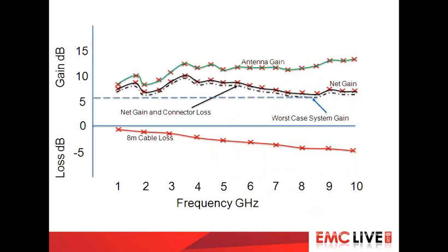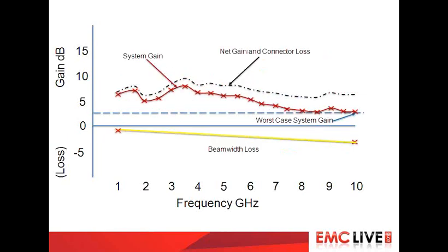So what do we have? We have a situation whereby, starting with your antenna gain across the band of interest that we're designing, and factoring in one by one the different losses, in particular, as I've introduced now, and I don't think I've seen other people do that, regarding beamwidth as a loss, putting that in as a loss too, you can get an overall gain. Well, there we go. We get an overall gain, and we can get that system-wide gain, plug that into the power required equation, and come up with the actual power that we need.